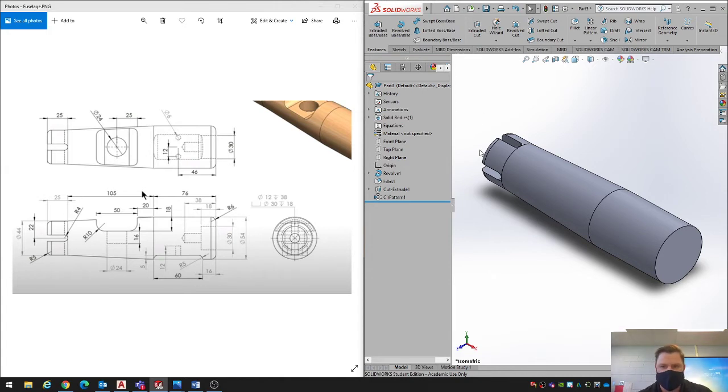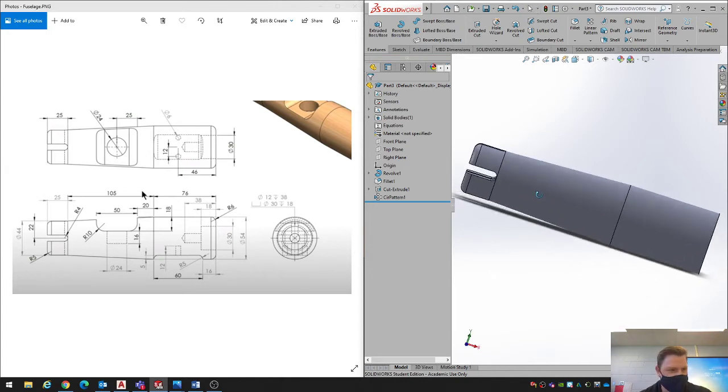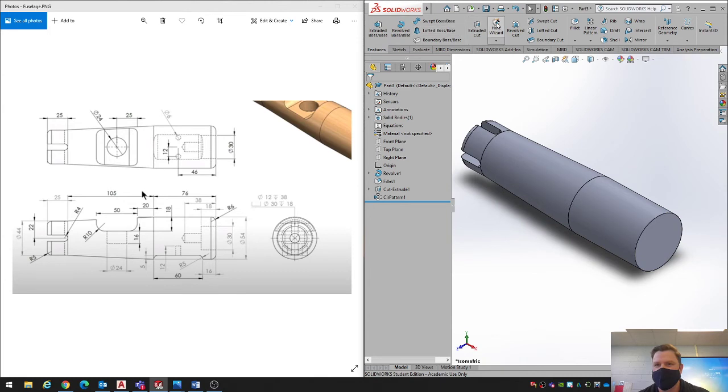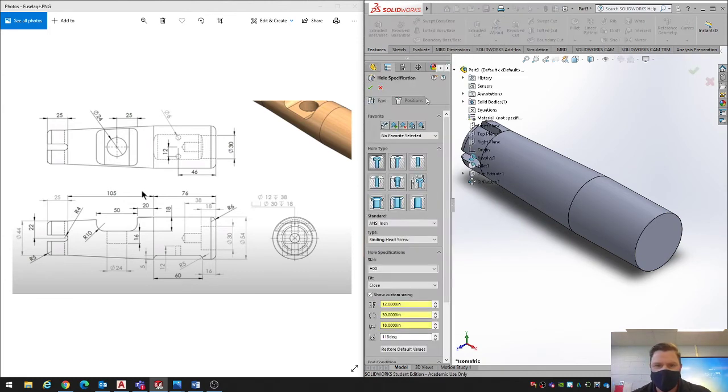The back piece looks done. We've got our fillet that looks okay, I believe. I'm going to skip these two and move to the front. I'm going to use a hole wizard, which I don't know that we've used before. So the hole wizard tool gives you different types of holes that you can cut into objects. This one is a counterbore type. So basically it comes in a little bit, and then the radius of the cut changes and it goes in a little bit more. So I'm going to keep it on that.